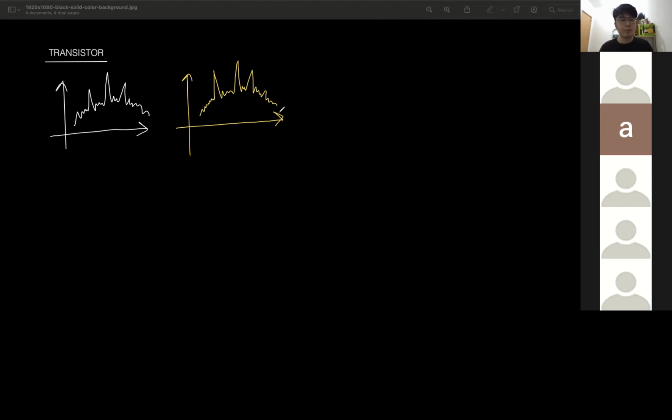Now, in the middle of the process, if there was no transistor, and straight away the microphone is connected to the speaker, then you cannot hear any sound coming out from the speaker. Why? It's because this electrical signal is too small to be heard.